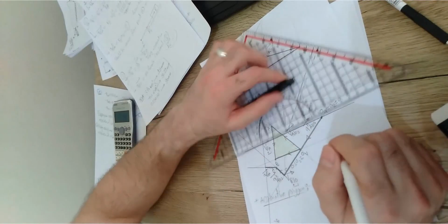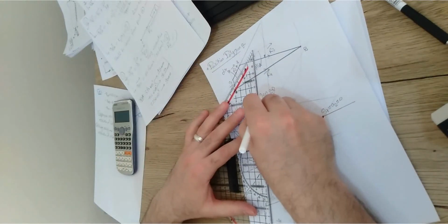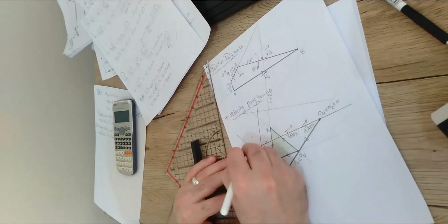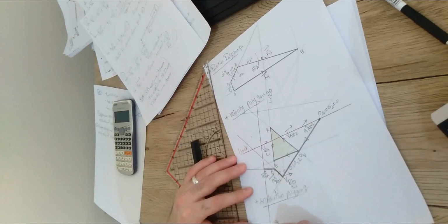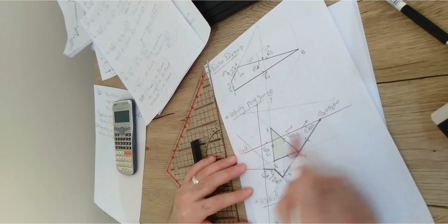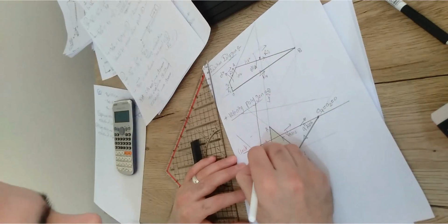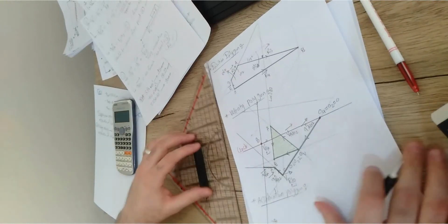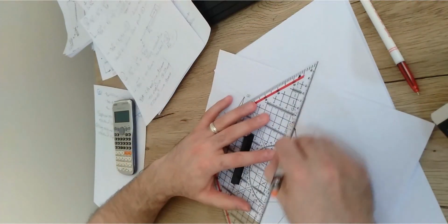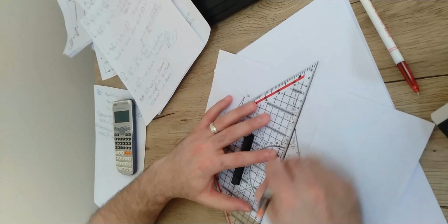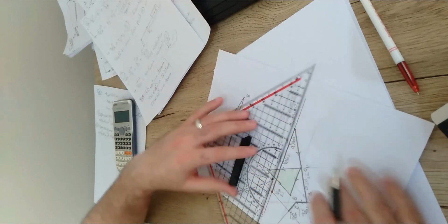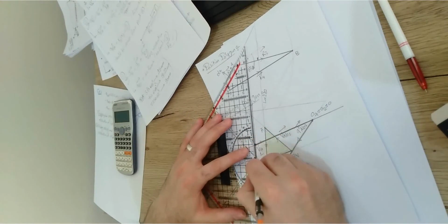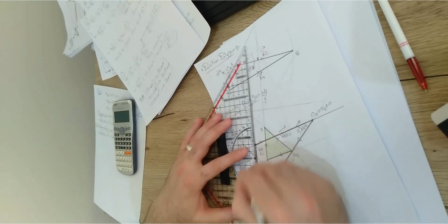This is the first locus and this is the second locus that we got from this point. So one locus, this is locus for point B, and this is another locus for point B. Both this line and this line are going to intersect at a point. This point definitely will be point B. Then simply you're just going to go over. I know that the drawing is kind of confusing, but I'm not caring about the velocity diagram that I already represented before. So then you're just going to go over this line.